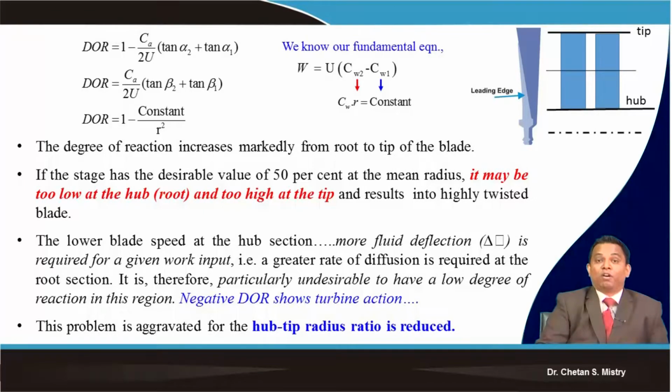It is not that people are not making designs based on free vortex. Yes, even today people prefer to go with the free vortex design, but as I told you, we need to be very careful in setting our degree of reaction near the hub region.